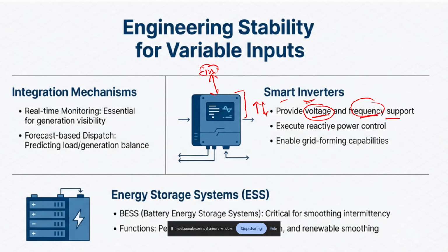And also these inverters can compensate the reactive power. As we spoke last time, the reactive power has to be maintained and kept in control. So continuously we have to inject this reactive power using the capacitor banks. There will be multiple capacitor banks which will have terminals, and these terminals will have different variables.